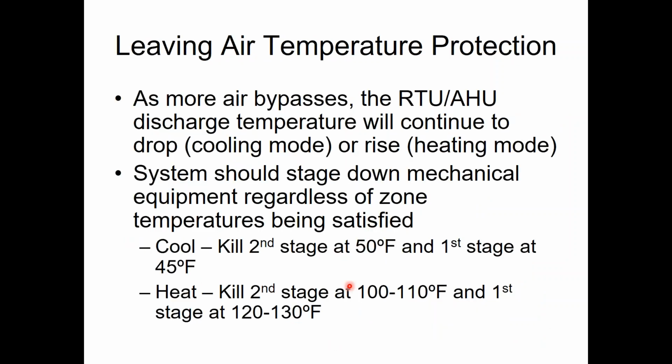All right, let's see here. I mentioned the supply temperature sensor for protection purposes. We will put a temperature sensor in the ductwork. And the reason we're going to do that is because as I'm throttling zones back and as I bypass more and more air, it's going to make my return air colder and colder in the summer, or in the winter, hotter and hotter. And when I do that, it's going to mean that I'm going to trip some limits in